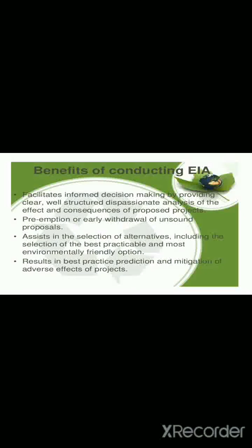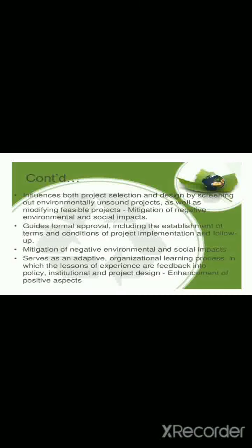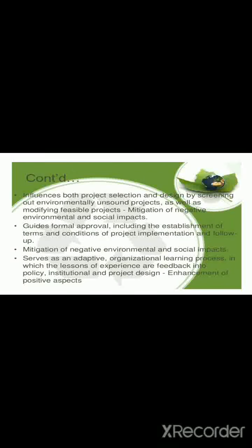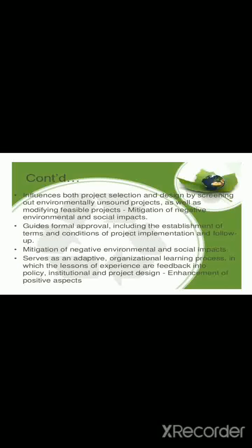Then what can EIA do? It influences both project selection and design by screening out environmentally unsound projects as well as modifying feasible projects, that is, mitigation of negative environmental and social impacts.